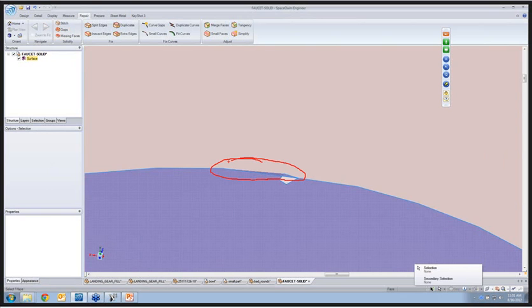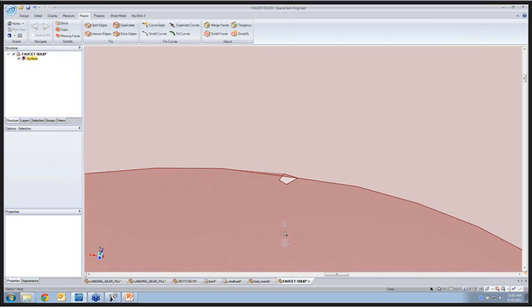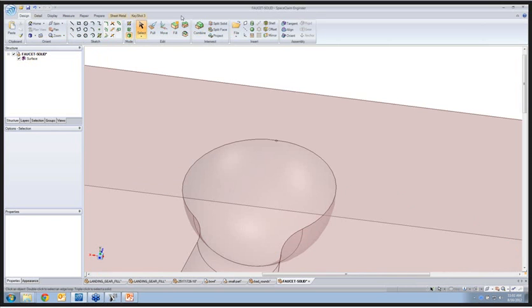This is actually corrupt data. It's very, very common with IGES files. You saw a little bit of it with the very first model we worked on. But it's not a pure missing face. It's just straight up corrupt data. And so the idea in SpaceClaim is, why try to repair corrupt data? Why try to heal that up in and of itself?